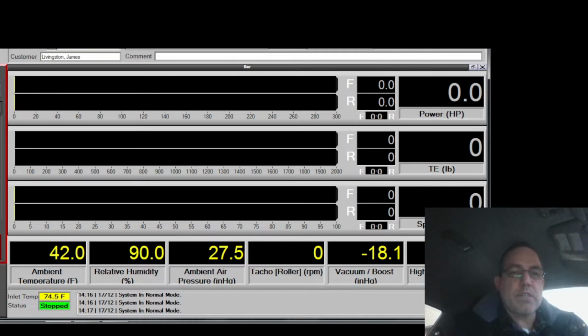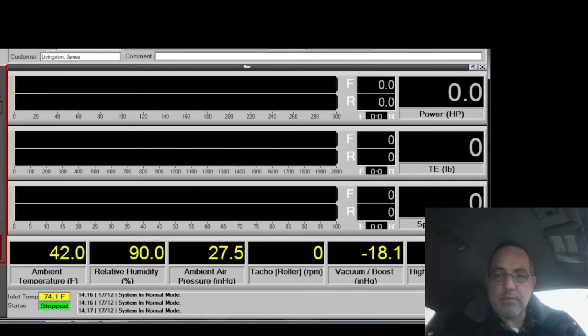I think I'm going to increase the amount of fuel at idle, change the target to be a tiny bit richer. When you have bigger injectors, you often need to do that because you can technically spend a lot of time going through the tune and, oh yeah, this is still the factory leaner than stoich target. You can spend a lot of time going through the tune trying to find exactly which cylinder is how much leaner or richer than the other ones and all of that.